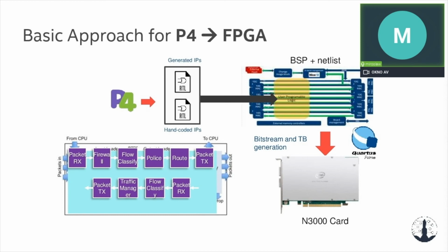Normally, when you have an expert in RTL design, you can put this on any card. But we know that people have big problems moving this RTL design to the real card, to the real FPGA, because you have transceivers, you have RAM access, RAM lines, PCI lines. You must implement some kind of host interface, how to access this card.